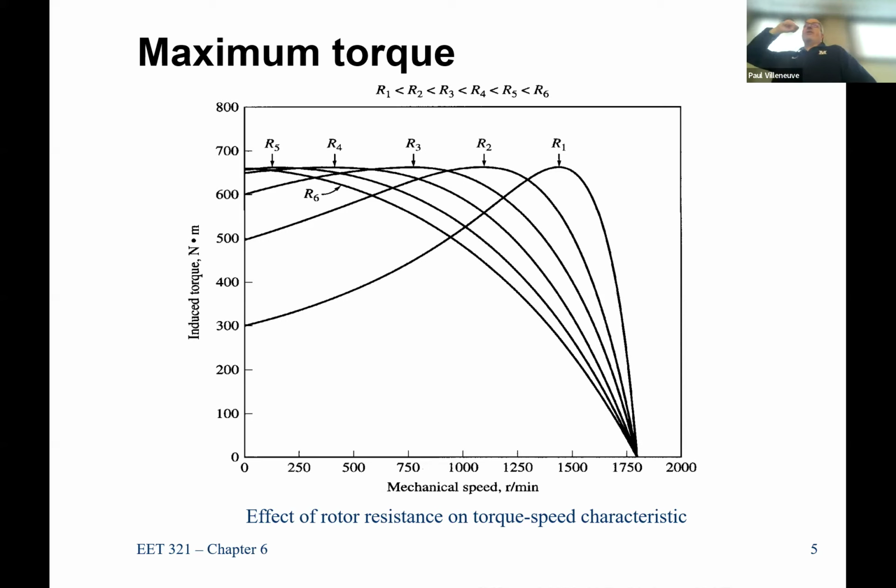But there's one reason you're all forgetting. Because you want it started off with a little bit less torque so it doesn't slip while starting. What do you mean slip? What would slip? Oh, the pulley. Remember, you're driving a mechanical load. So you're saying the belts would slip?